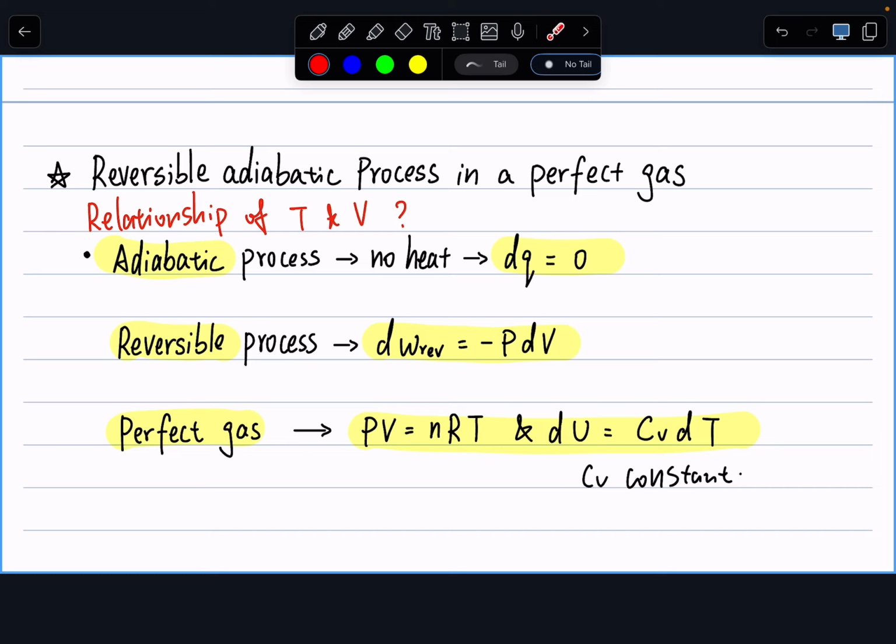This is the only universal definition of Cv. Cv by definition equals the partial derivative of internal energy with respect to temperature at constant volume. But in special cases, we can write, for example, Cv equals dQv over dT. That is because dQv equals dU for special cases.